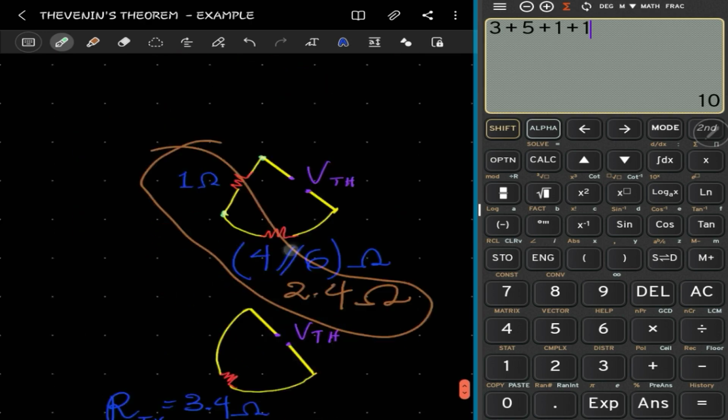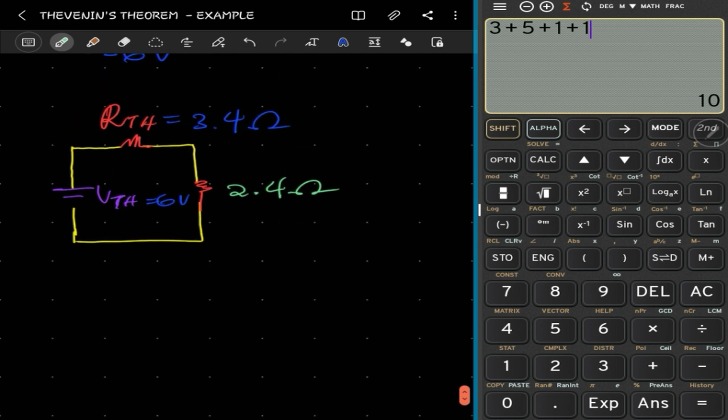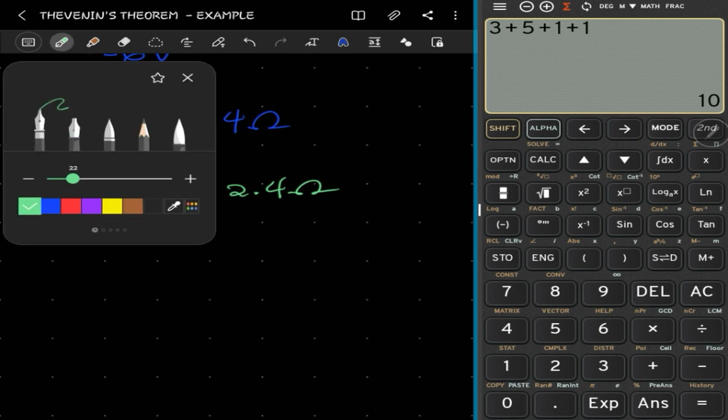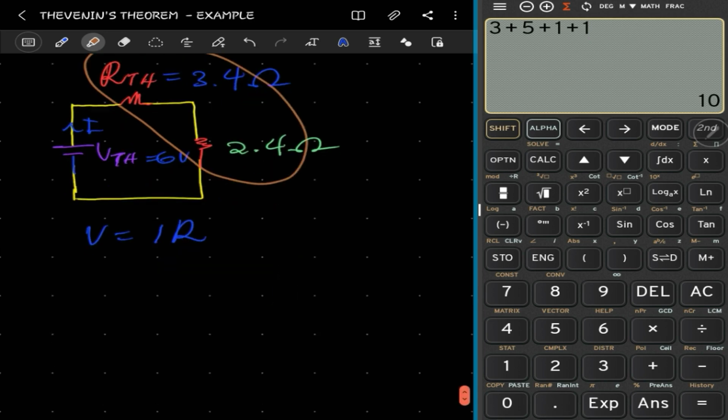2.4 is 2.4. Right. So now that we have this, based on Thevenin's theorem, we've simplified the whole diagram to this. That will mean that the whole equation, as we've said so far, is V equal to I, right? And if you're trying to find the current through this, we know the current supplied here, right? I will pass through this and this, right? So this and this are in series, so the current passing through them is the same. So what we'll do is find the total R, and the voltage that we use is VTH, right?